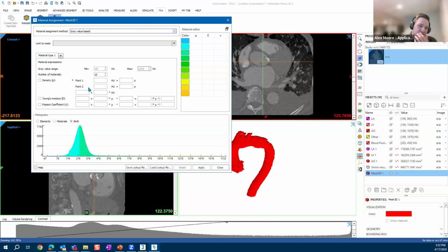I don't have anything for soft tissue, but I know in the help guide of Mimics, we've gone through literature and put together tables for hard tissues like bone, cortical bone, spongy bone. We do have some values there, but that was just taken from literature. Those density values, the Young's modulus, you would just be able to go in and enter that, and it would take your intensity value, put it into here, and then assign the material properties to individual voxels.